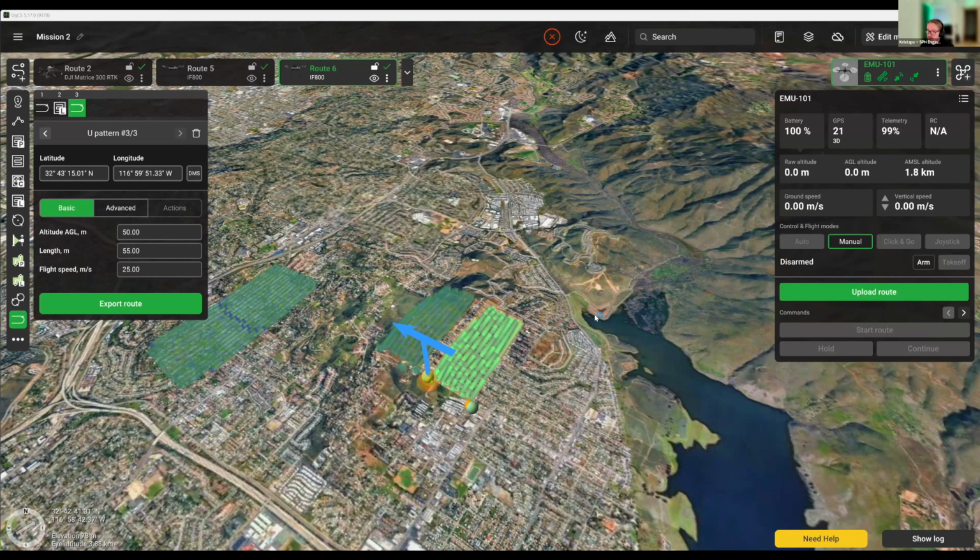With this method, you can upload the route directly from UGCS. So that means if for the M300 you're using either the UGCS companion app or UGCS for DJI, which is for older drones, but it also includes the M300, then you can have access to all of these actions here to upload the route, start it, and so on.